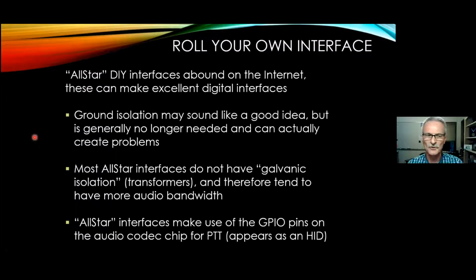Most of our computers these days operate off of a power pack that doesn't even have a ground connection on it. Or if it does have a ground connection, it's probably not tied to the negative side of the DC output going into your computer. I very rarely see any kind of ground loop condition going on these days. The other big problem with utilizing transformers is that they're going to limit the amount of bandwidth you have available, limit the amount of audio bandwidth.